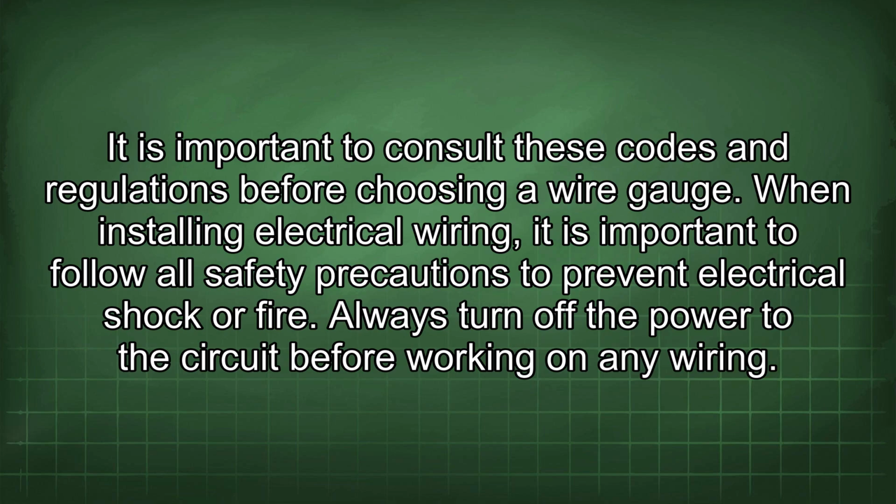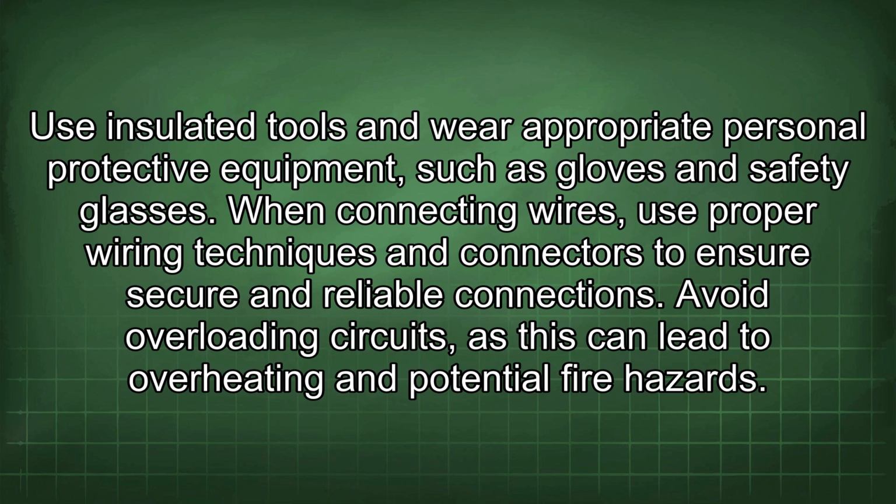When installing electrical wiring, it is important to follow all safety precautions to prevent electrical shock or fire. Always turn off the power to the circuit before working on any wiring. Use insulated tools and wear appropriate personal protective equipment, such as gloves and safety glasses.